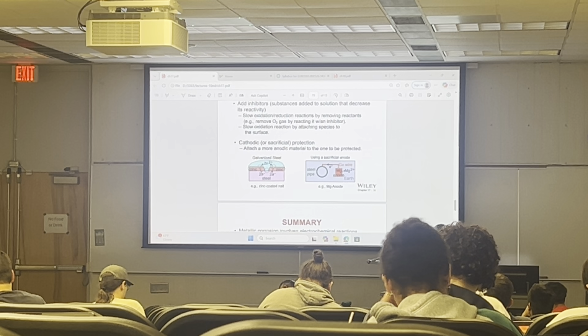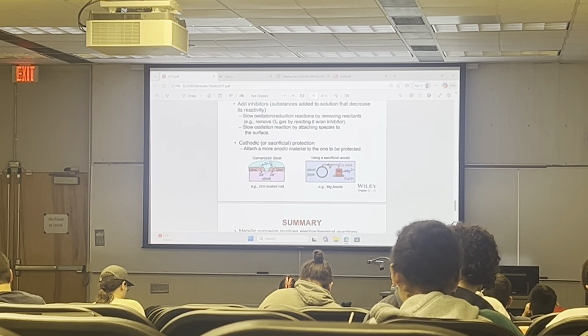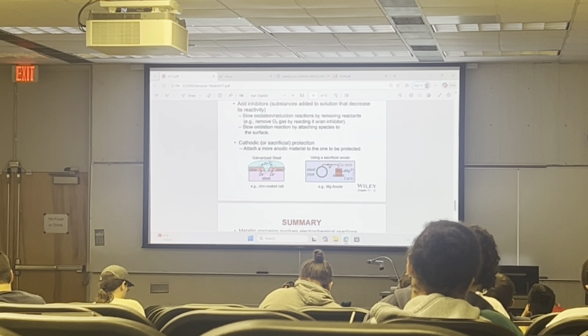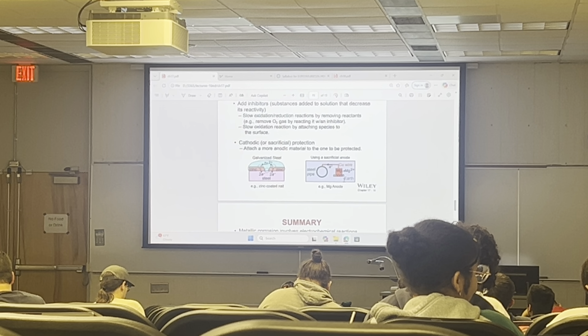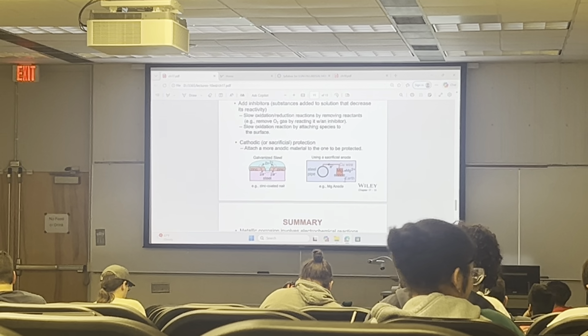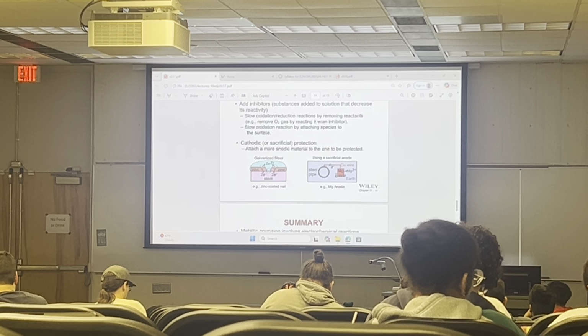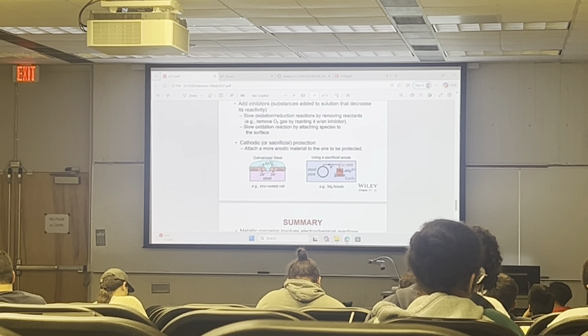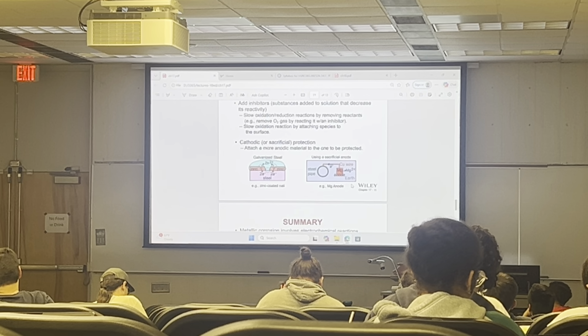For the civil engineers, the sacrificial anode, primarily magnesium, can be connected to the rebar, or in this case it's steel pipe. Like this is underground. Whenever you do corrosion protection for the structure, you have to be careful because this magnesium anode is expendable. You're going to use this material up. So you would need to make the calculation of how long it's going to take for this thing to get dissolved, and once this is dissolved, there's going to be a hole in your structure.